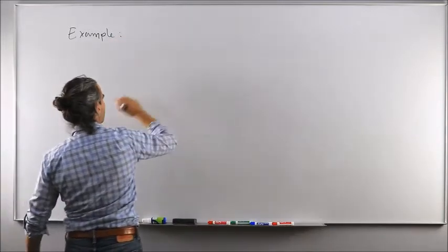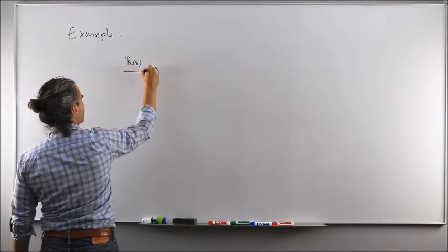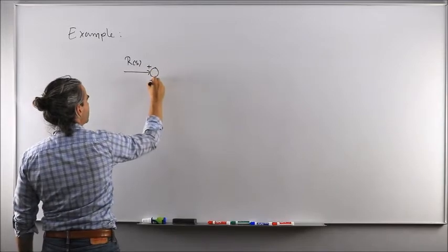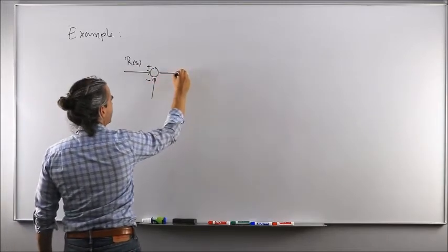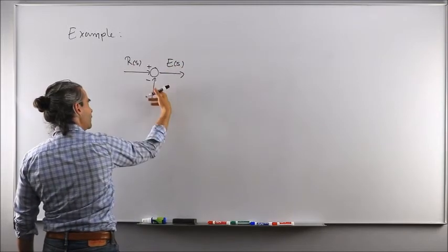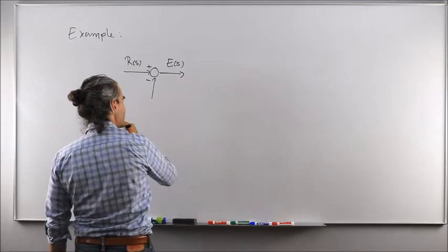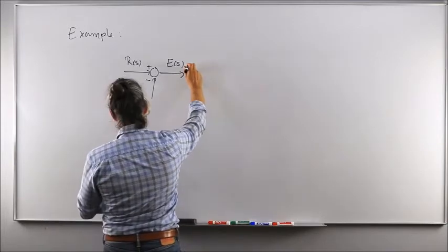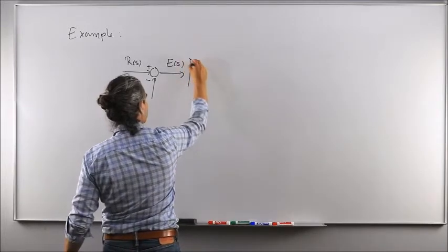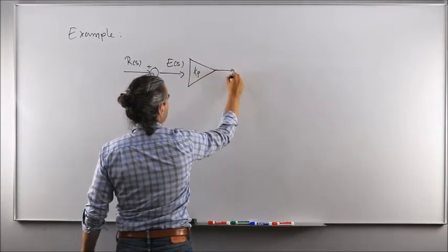Okay, so let's go back to a block scheme diagram. I have my reference signal here, plus, minus. This provides me with the error between the reference signal and the actual output of the plant, being the rotational angle in our case. This is being fed to my KP term of my modified PD controller.